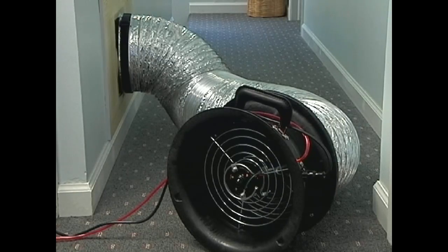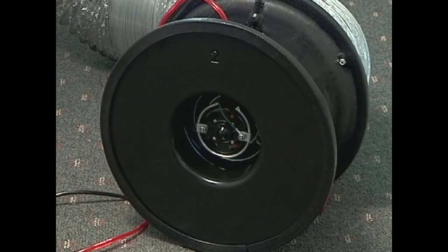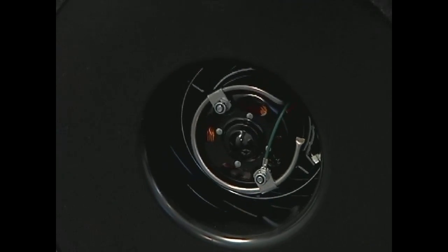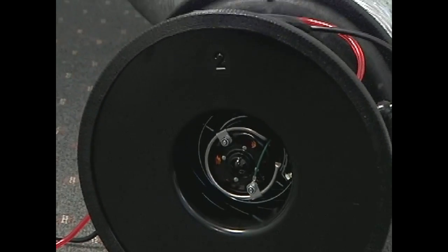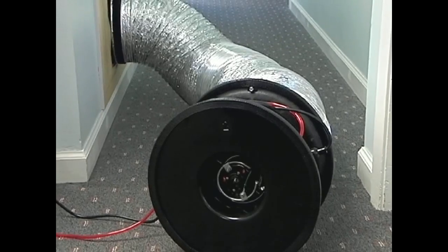As the duct systems you test get tighter, you will need to install flow rings with a smaller and smaller opening. Flow ring number 3, with the smallest opening, is used on the tightest duct systems. When in doubt, start with flow ring 1 or flow ring 2. Don't worry if you make the wrong choice. You can change the flow ring during the middle of the test.